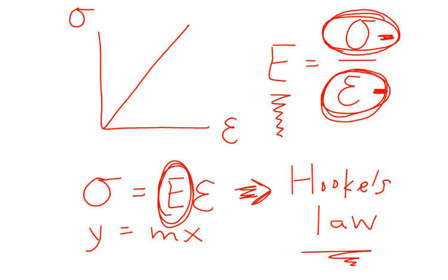Let's think a little bit more about what Young's modulus really means. It's a material property, and it's basically a measure of how much something deforms when you apply a certain amount of stress or a certain amount of load to it. So another term that's used out in the real world, at least, it's not a technical term, a lot of times this is referred to as stiffness.